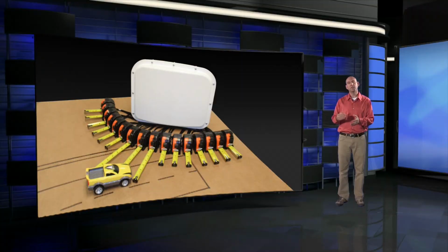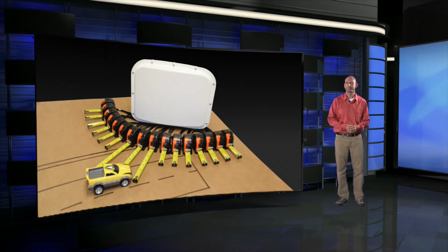The illustration may imply that it's only measuring the distance to the first target. That's not the case. It actually measures the distance to all the targets that are within the field of view of the antenna beams. It makes these distance measurements 3,600 times a second out of any one of the 16 different beams. It combines all of this data, all of these range measurements from all the different beams, into one image that is then used for doing traffic detection and for monitoring the vehicles as they travel along the approach.